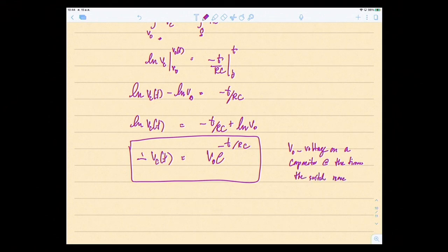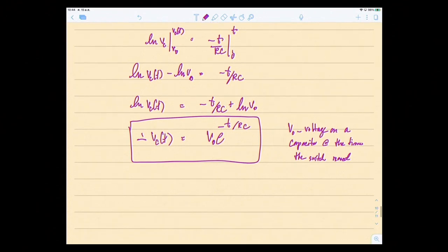Okay, well, the way this voltage looks like, so this is your Vc, right? So at t equal to 0, e to the 0 is 1, so you have V naught. And as you put in t equal to 1, t equal to 2, it would be sort of like minus exponentially going down to 0.